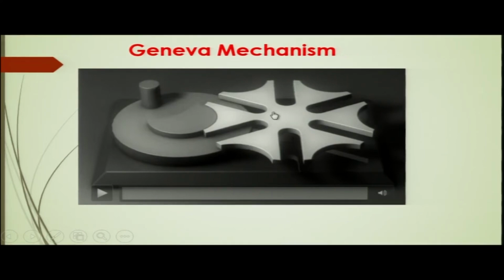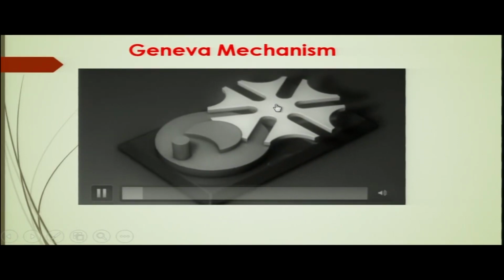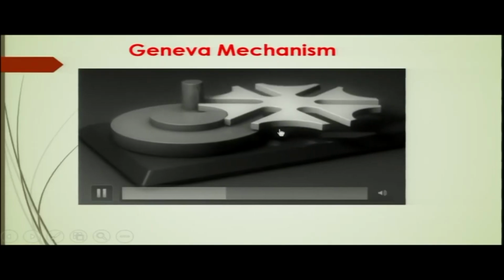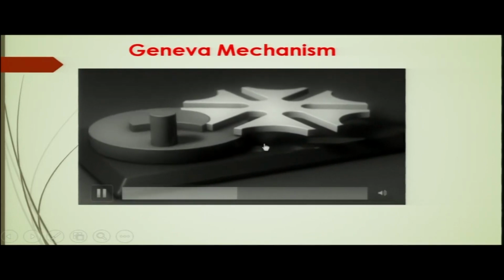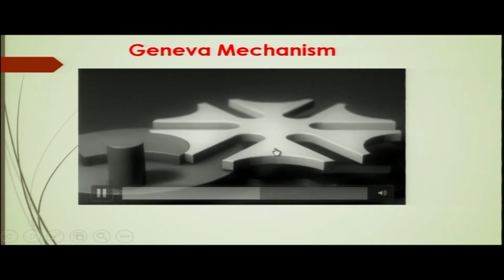Entire load, I mean to say that on this output shaft of the Geneva mechanism you have a table, and on that table you have heavy machinery, let us say heavy sub assemblies. The sub assemblies will be located directly on this position, and here we will have the machines. The machines are not located on the Geneva wheel, but the sub assembly has to be here.